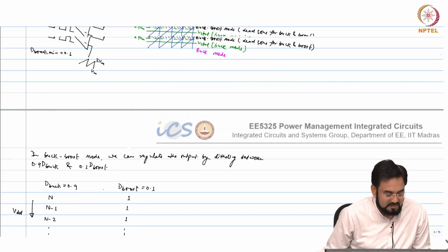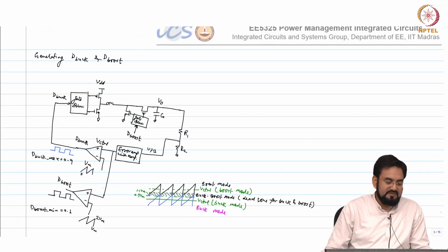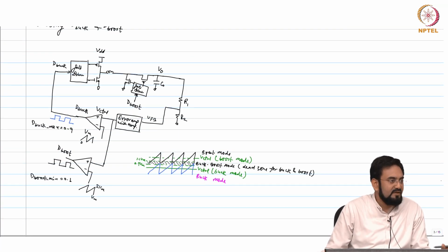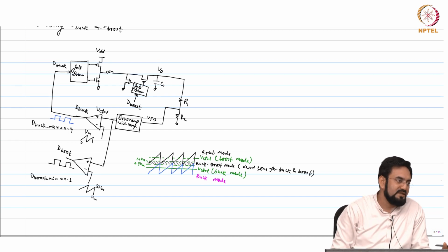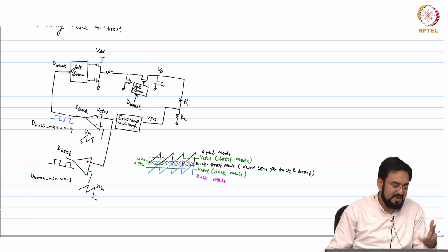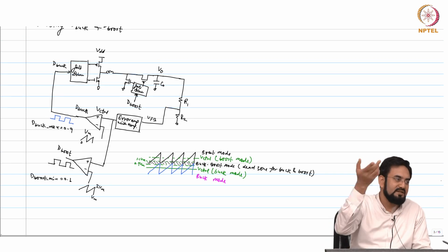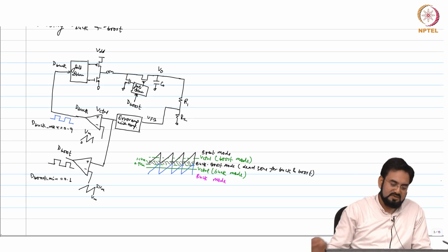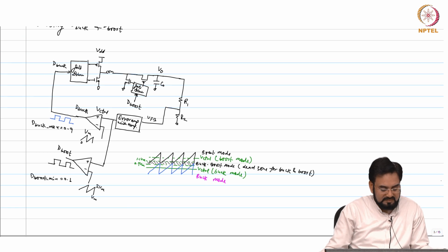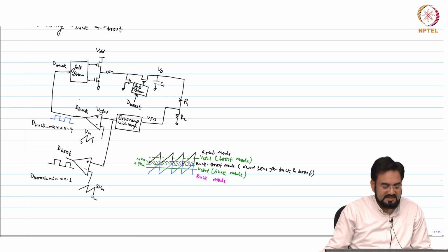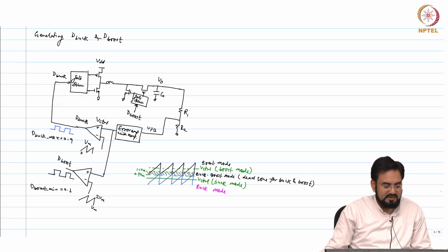Otherwise, if you want to do it in analog, then the only option is you leave it on its own and your loop will recover, but then you have to live with that transient, or you make your loop somewhat fast, or find some way to compensate, like feed forward compensation or anything to correct the duty cycle. You can do that also. In one buck boost we did, we simply changed the duty cycle.